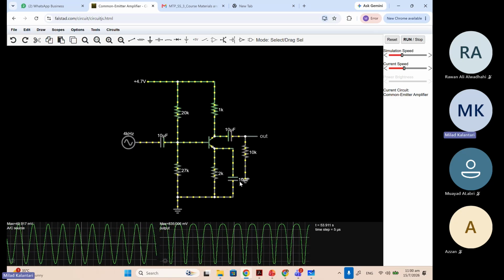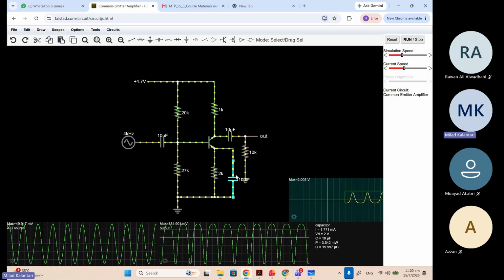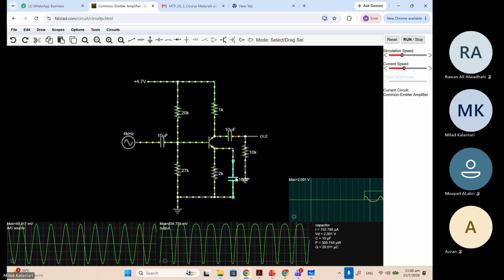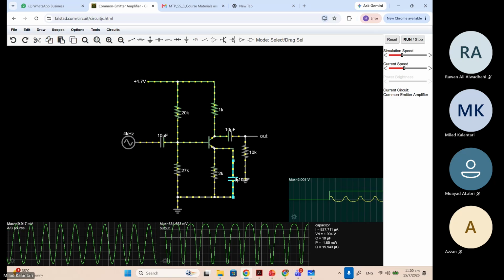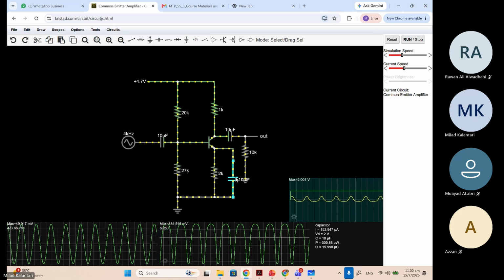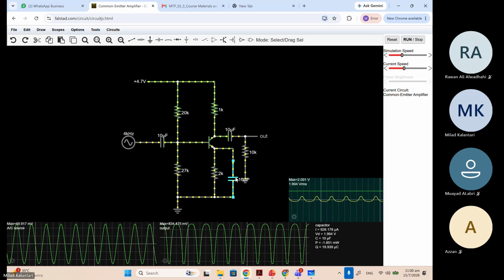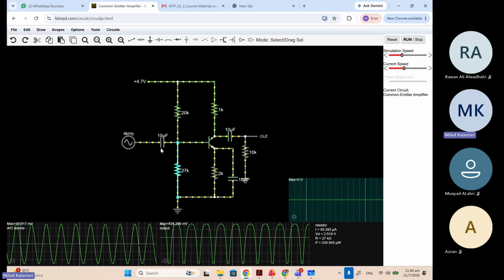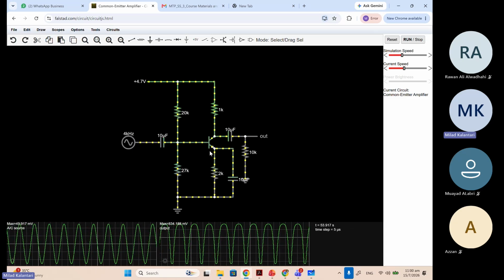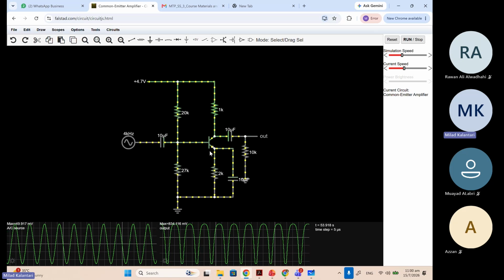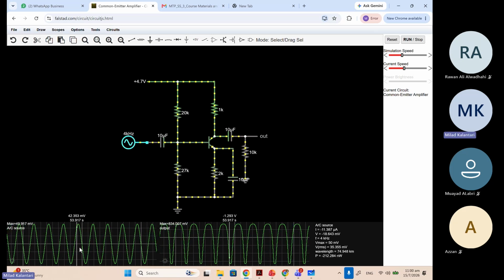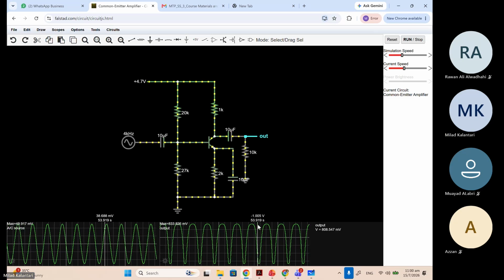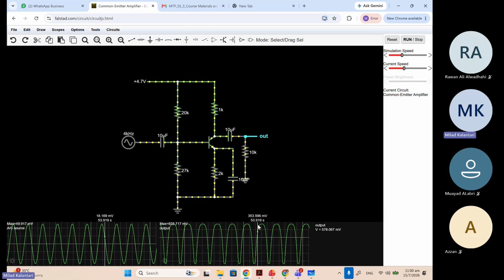No, the capacitors cannot do some. Actually, the capacitors, you can tell that they are short at this frequency. It is a distortion, right? The distortion means what? It means that your circuit is not linear anymore, right? So the input is something sinusoidal. It has changed it to something else, right? It's because of some nonlinearity of the device.